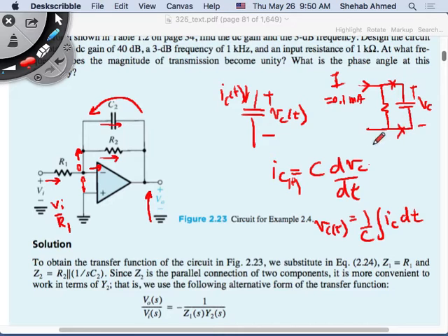If the capacitor becomes an open circuit, then I just have this resistor. So at infinity, if I keep this DC source there, what is this going to look like? An inverting amplifier, just a normal inverting amplifier, if I keep this DC signal in there forever.